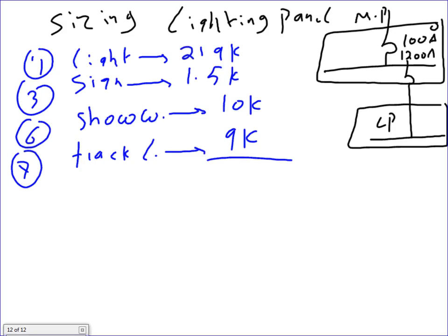These are all the loads that can be fit for lighting panel. Who decided? I decided. They are lights. That's why I put them on lighting panel. What's the sum? 239.5 kVA. Okay, piece of cake, guys. Then I will size the same thing. I will size first the panel for this one.